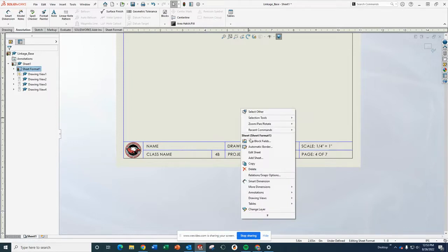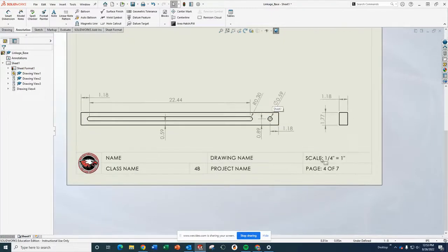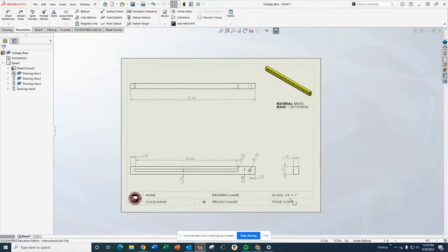And then when you right click, edit sheet, unfortunately, it's not in the same place, but if you just go edit sheet, then you'll go back. Your changes should still show. This all goes to black and gray. And the rest of the drawing is done. This is how you will complete the drawing and have it print ready, is the term we're going to use. So it's ready now to either actually print if it's for certain things, or if it's for an activity where you're turning it in digitally, it's now ready to take your screenshot and turn in using that process.